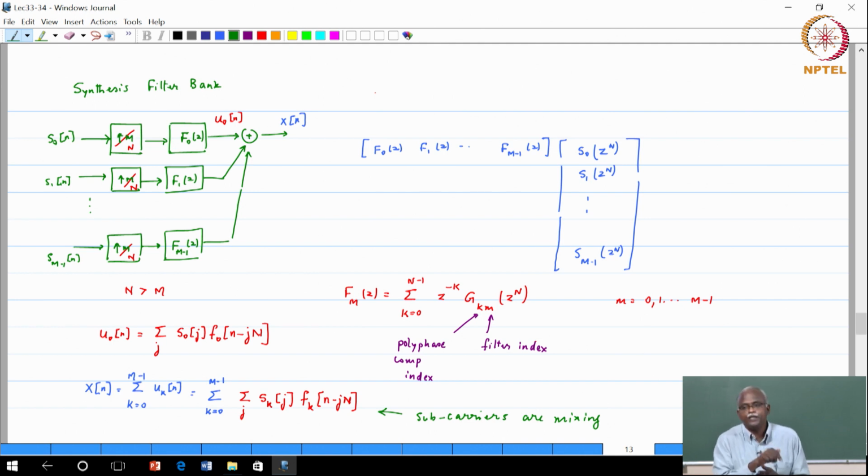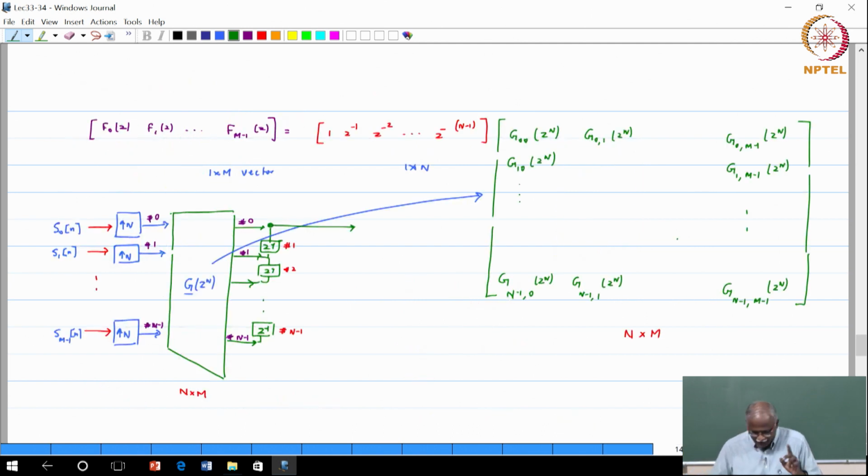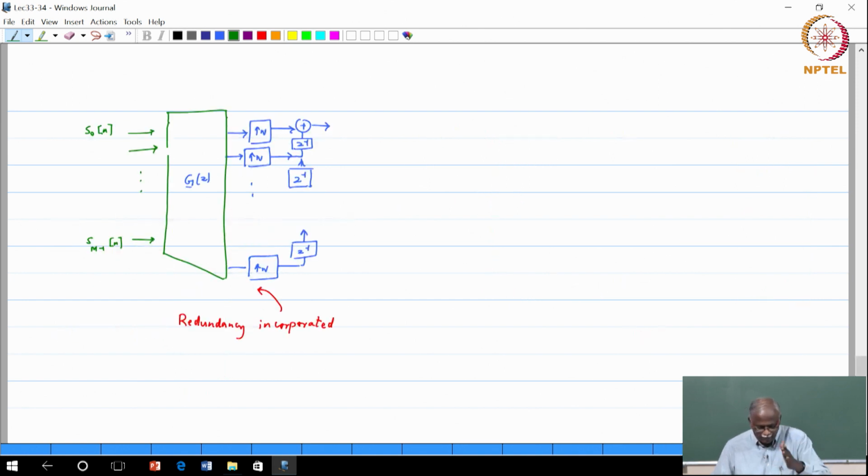Now, if I want to get efficient polyphase implementations, I must do the polyphase decomposition and apply the noble identities. So, now I need to split it into n polyphase components, though I have only m filters. So, again this is the way in which we have developed the notion of redundancy and how we want to move it forward. Okay. Now, let me just add one more element, and then we will conclude this section and take a short break. So, I hope this representation using the trapezoid is comfortable. Then the application of the polyphase component is also.